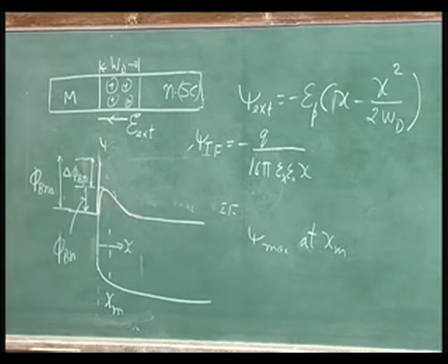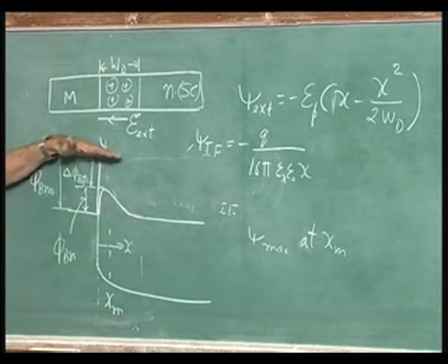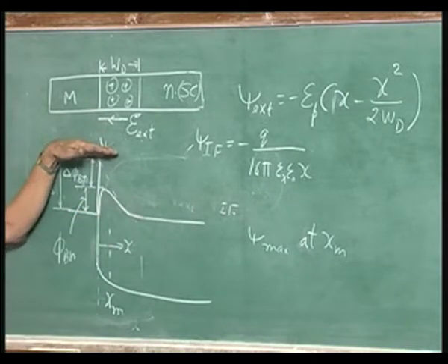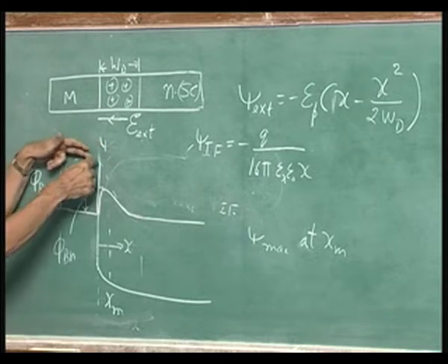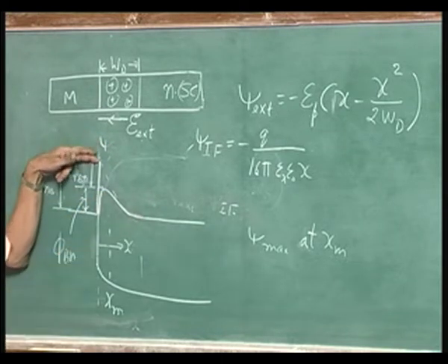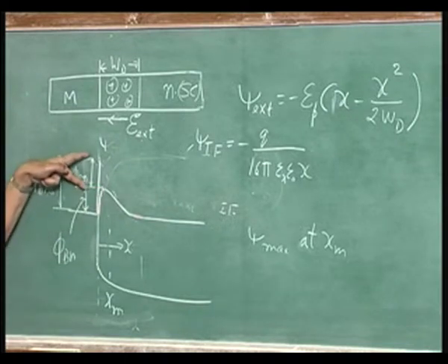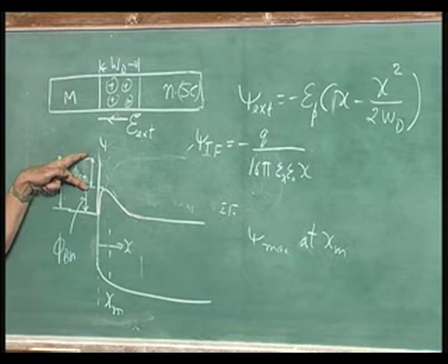See, please remember, the potential we are drawing, taking this as 0, with respect to that, how much is it? The psi that we put there is psi with respect to that, because that was 0 there and that was psi image force. If I take it as 0, that is the potential. So, if I find what the psi value is here, that straight away gives me delta phi B n. And how do you find the psi value there?